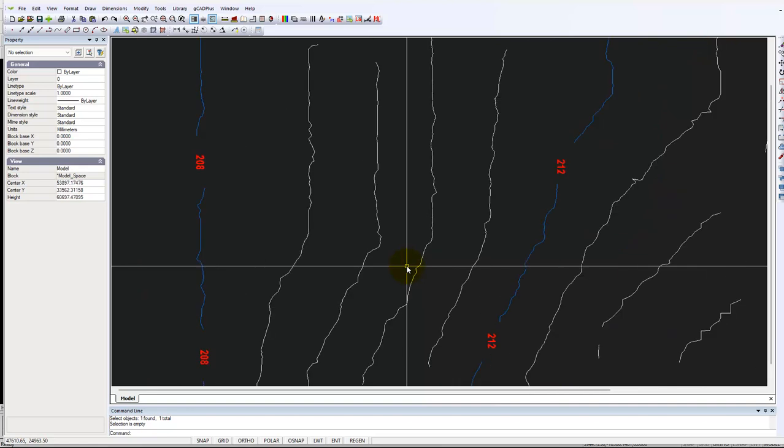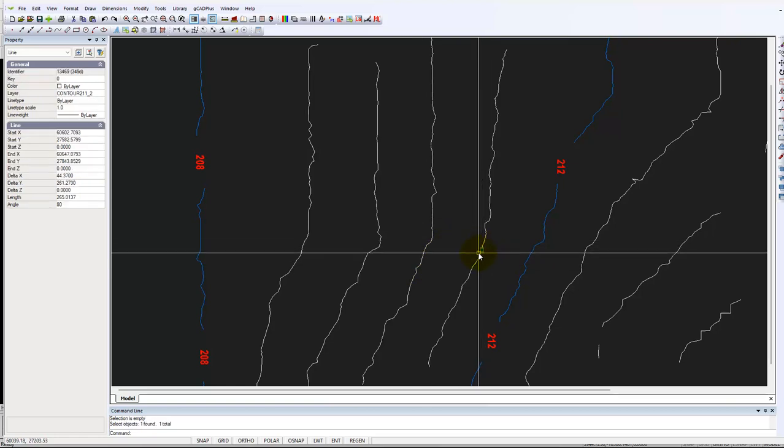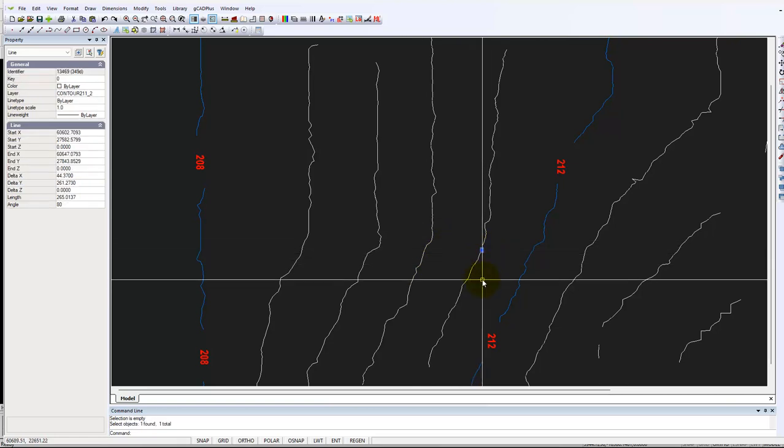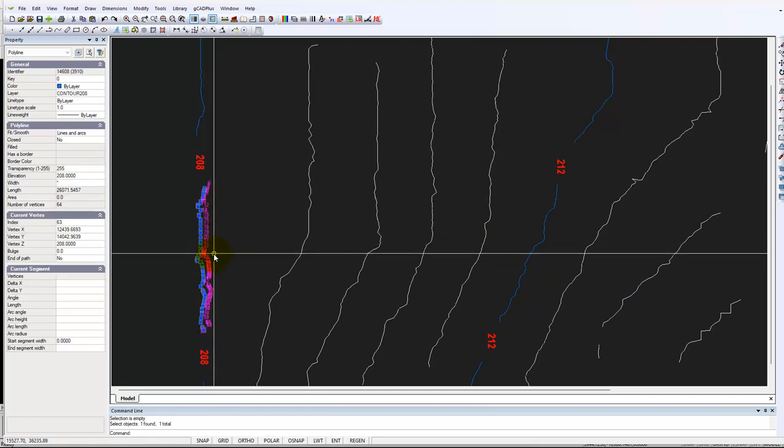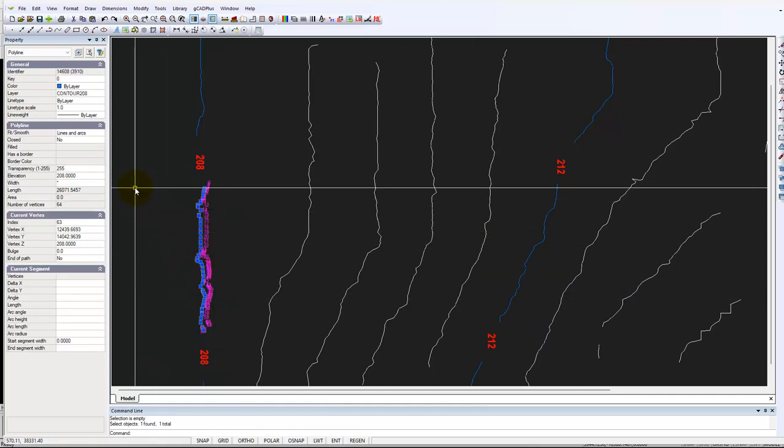And if you have to work with a drawing such as this, and you want to extract point data, you do need to be aware that extracting point data usually involves extracting the data from a polyline, and so we need to turn the short line segments into a polyline, and I've done that over here. So there's our polyline line segment. Notice polyline.